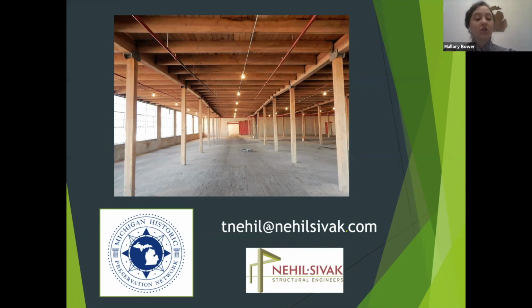Do barn structures usually have a certain species of wood for sill beams as compared to the posts in Michigan that you've seen? Well, they should, and they don't always. We have come across eastern white pine being used for sills, and white pine is okay for siding, but as a sill, it's really not a very durable material. I have seen quite a bit of poplar used, yellow poplar, it's called officially, but tulip, and that's a fairly durable wood. Again, really great for siding and other things.